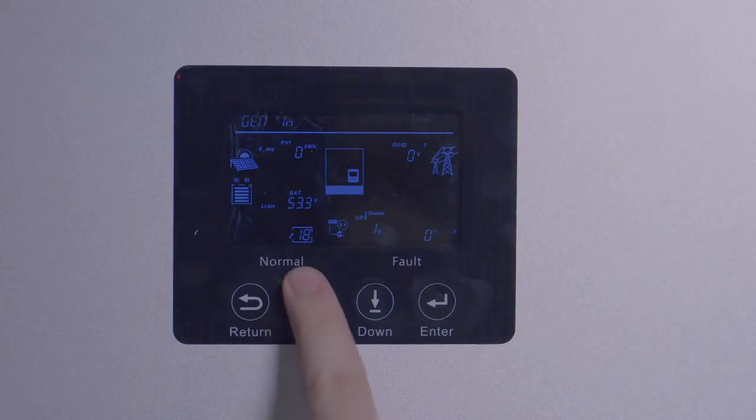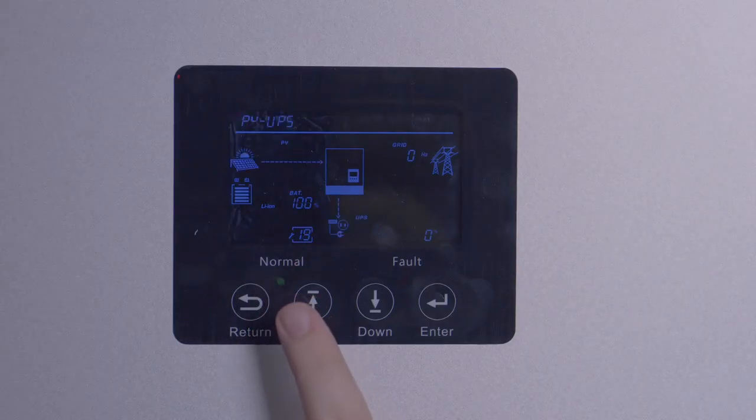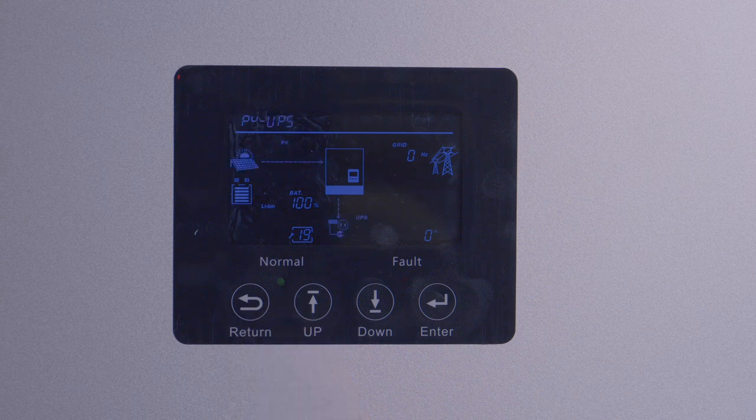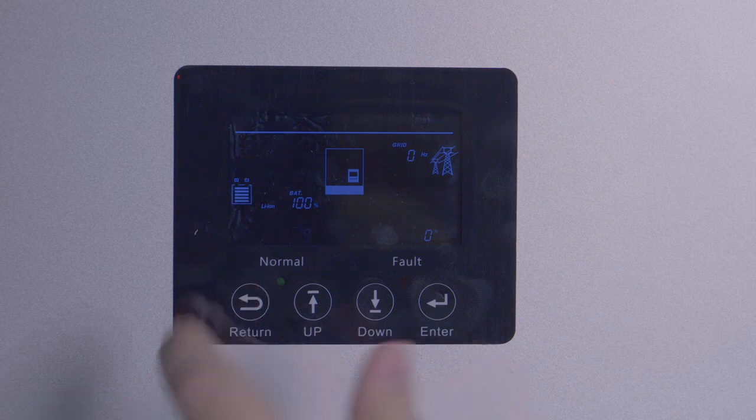Setting 19 is the PV backup power. This allows the inverter to input solely from PV. Due to the fluctuating nature of PV input power though, there's very few niches that this setting needs to be active for.